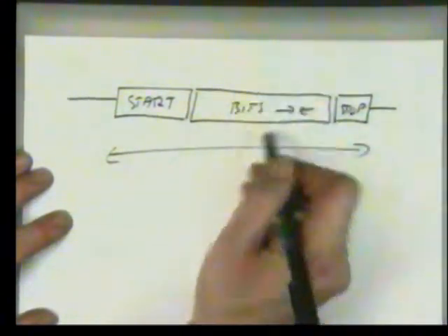Let's look at the structure of what happens in here. As with SPI, all data is transferred in bytes, 8 bits at a time, most significant bit first, bit 7 down to bit 0. Whenever a byte is transmitted, regardless of whether it's sent out by the master or by the slave, the receiver always acknowledges receipt of that byte. And it does that by outputting a logic level 0. Why is that? Why a 0?